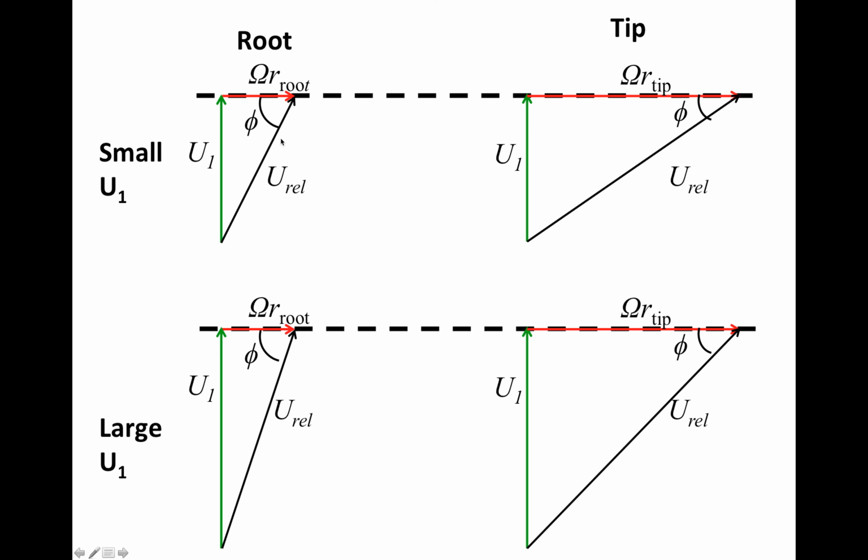If the phi is larger, which means what? Which means the angle of attack is going to be larger, suppose the twist angle is about the same. For a small wind turbine, you may not have a twist. The blades may not be twisted. So let's suppose there's no twist. If the phi is larger, then the angle of attack is larger.